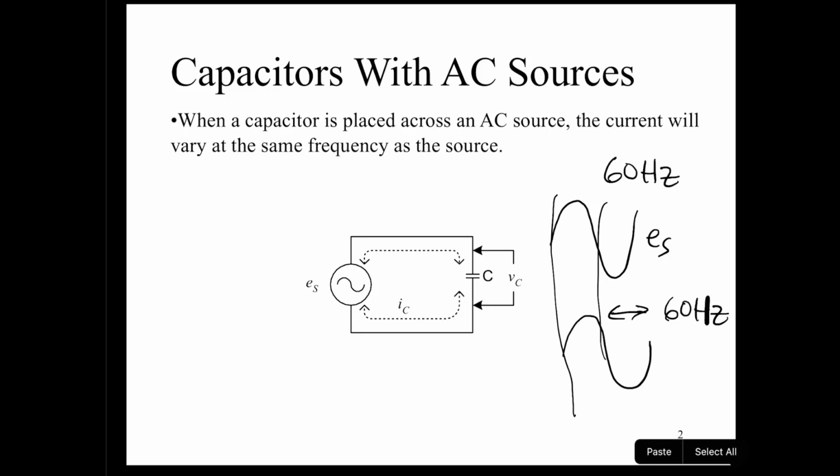And this is something we call the circuit phase angle, right? If we had a purely resistive circuit, R as our load, that means our phase angle is going to equal 0 degrees and everything's going to be in phase. If we were to look at an inductor, a pure inductance L, then our phase angle is going to be 90 degrees. We're going to have a 90 degree shift between voltage and current. So let's see what it looks like when we look at a capacitor.